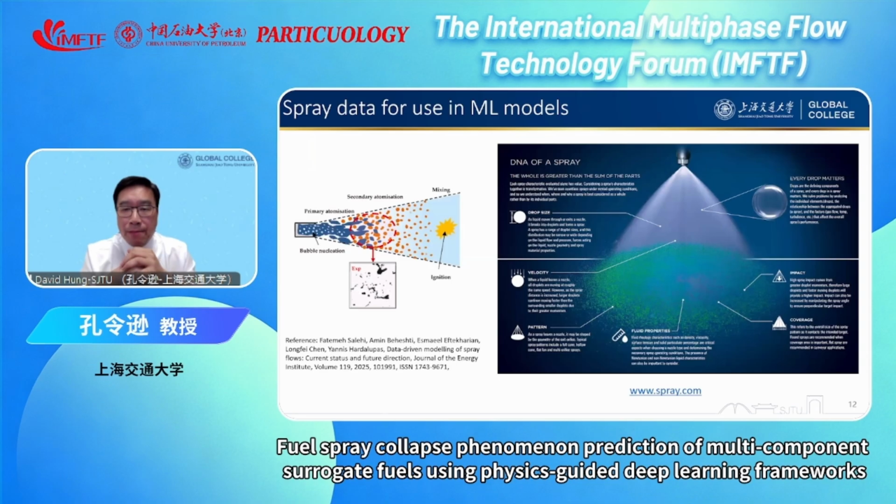To put it this way, if you look into the spray, there are a lot of things that we are studying. The drop size, the velocity, the spray pattern at different locations, and whether they are primary breakup or secondary breakup. And if you use different liquid like molten metal, it's very challenging. If you use fuel spray, you have to consider evaporation. If you look into something more exotic, you have to consider non-Newtonian breakup. So I think this is quite exciting in my domain.